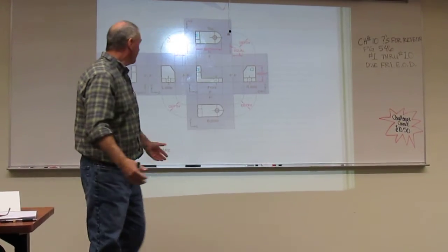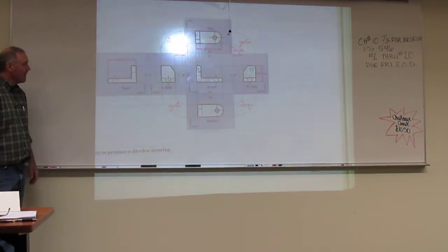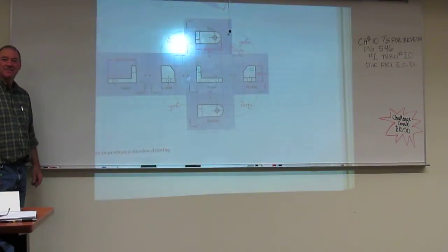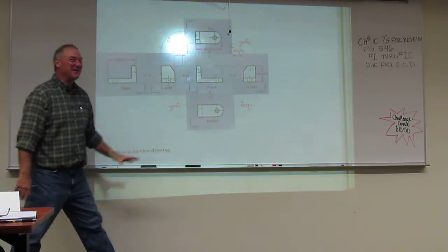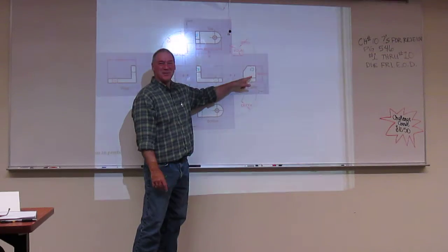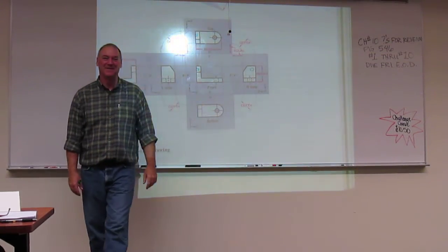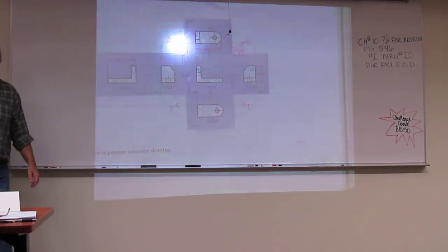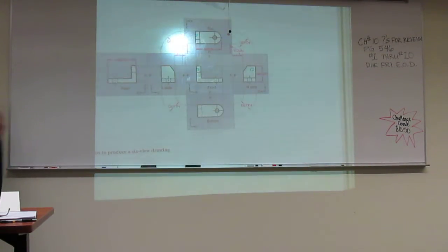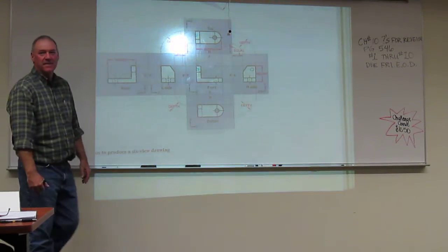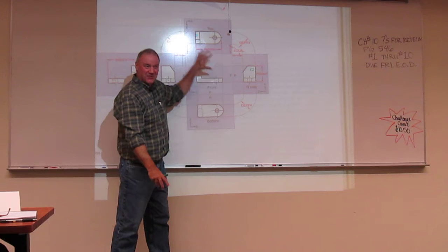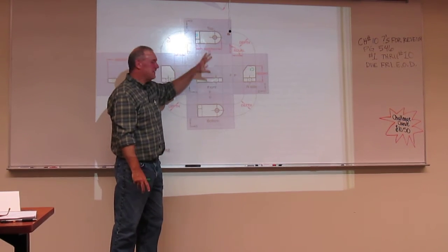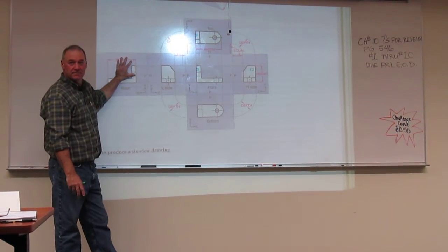So in this case, what would I do? Oh, that's a toughie. To be honest with you, I'd pull out one of the sections that you haven't learned yet, and I'd put these three, the front, top, and right, but I would use a process called a broken out section to describe that. Is it typical that you wouldn't just do front, top, and left? If you need a left, you're going to give it the right anyway? No, I'm not going to say that. This is where we want to try and stay. That's your guideline. If you need to delve outside of that, yeah, you have these available to you.